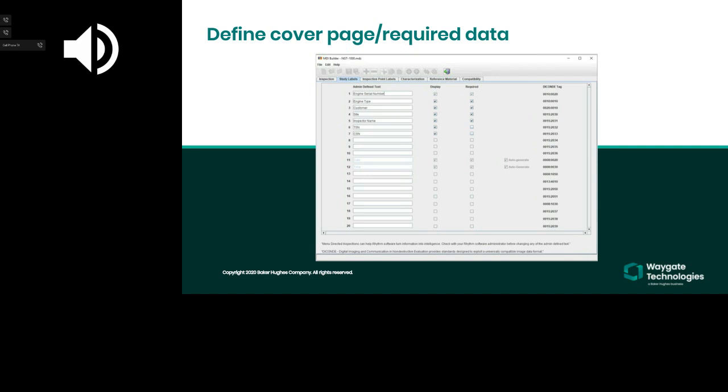It's Digital Imaging and Communication for Nondestructive Evaluation, and each piece of your data can be meta tagged, so you can say, show me everything that Bob inspected on a heat exchanger in the plant and on what date. And that information is describable and definable by you when you're building it. And you see those 18 different fields. There's 20 of them, but 2 of them are DICONDE tagged to date and time. They're available for you to customize this to meet your exact operation.